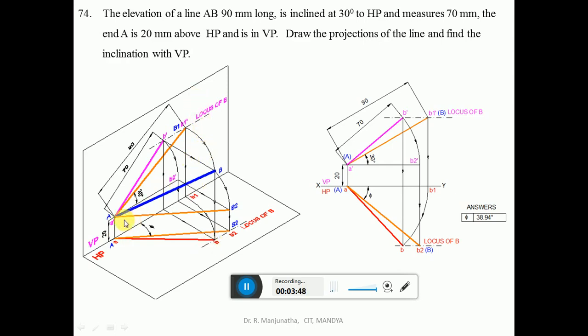The point A1B1, that is A dash B1 dash in the front view, is rotated such that this point B1 dash, that vertical line of the B1 dash, will come on the end projector here, so that you are going to get this distance. So this point will form capital B, then join capital A to B with a dark line. So this is the actual line in the 3D.